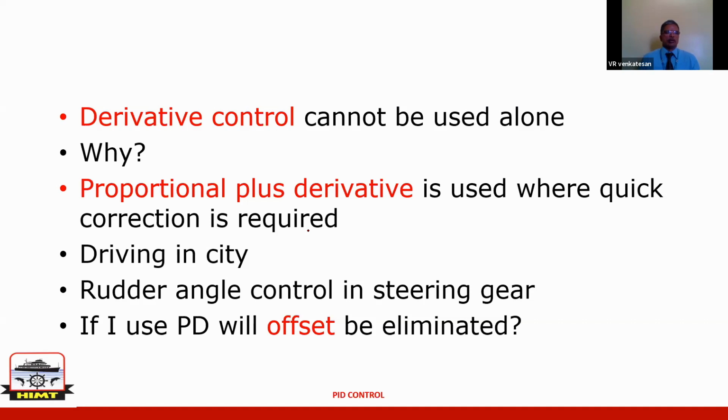But in steering gear, you think that the rudder has reached the required angle. I want 20 degrees in rudder position. Rudder reaches 20 degrees. Do I still need an output? No, sir. I don't need. The pump can go to zero stroke.